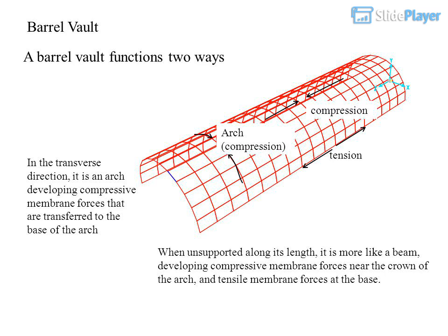Compression. Arch, compression. Tension. In the transverse direction, it is an arch developing compressive membrane forces that are transferred to the base of the arch. When unsupported along its length, it is more like a beam, developing compressive membrane forces near the crown of the arch, and tensile membrane forces at the base.